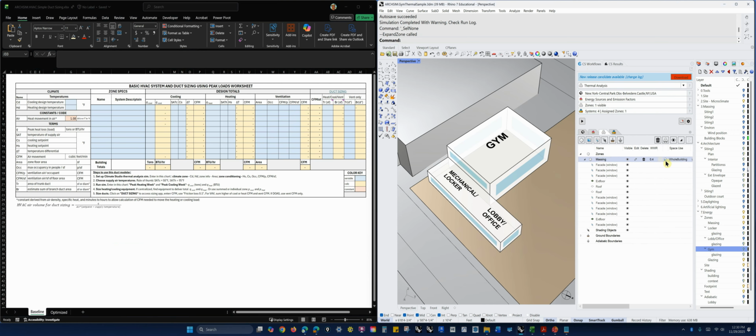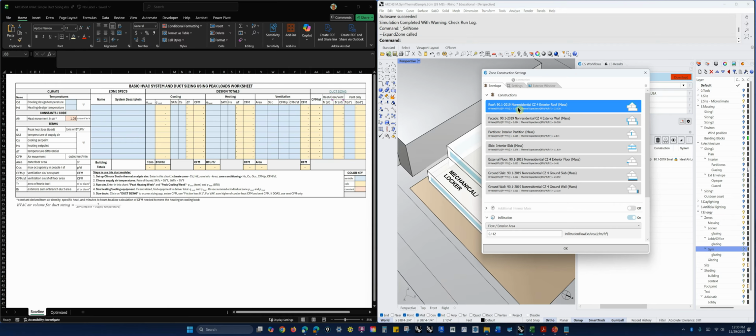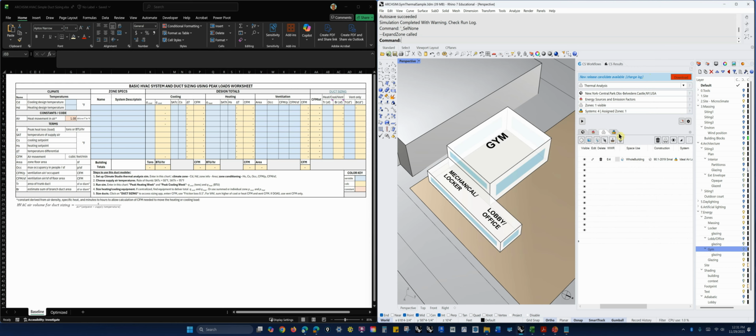And then I pick templates and settings that I think are relevant to my program. So I've got, for example, I'm using 90.1 envelope. I've got basic air tightness, as I understand something about that, and I'm using a window-to-wall ratio of 0.4 because that's the code maximum.